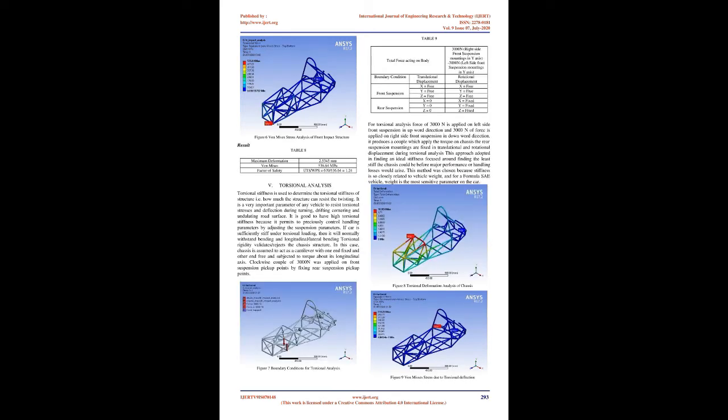For a structural analysis problem to be solvable, every location on the boundary of our structure must have a known boundary condition. For example, we may know that there are locations on our structure that have no external force. A displacement boundary condition that is 0 is equivalent to the structure being held in place at that location. They simply impose deformations on boundaries in your model, usually equal to 0. Each point in space can translate in 3 directions and rotate around 3 axes.